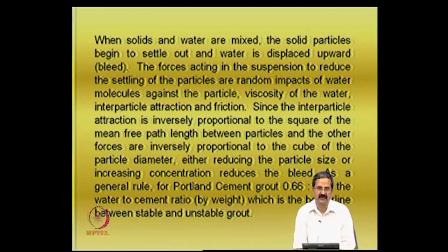See, in the case of grout, imagine that you are doing a hydrometer test. A hydrometer test is a simple example of a slurry. So the forces acting in this soil suspension or grout suspension, we try to characterize in terms of the Brownian motion, but here in this case the impacts of water molecules against particles, viscosity of the water, interparticle attraction, and friction.